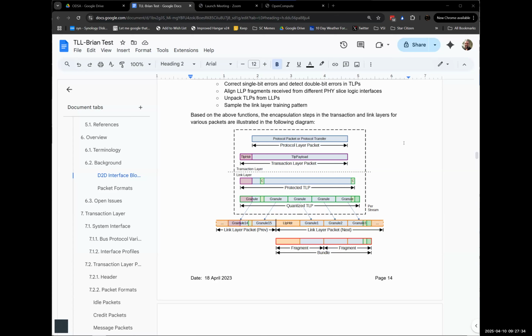It breaks up into two code words. One of them is 32 bits. So it's basically your TLP header, which is like 12 bits plus some payload plus some ECC. And then every 128 bits, I want to say, we have another ECC. That's your large code word. Every 128 bits or so, we have another ECC byte.